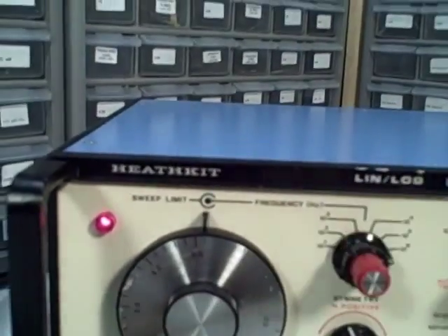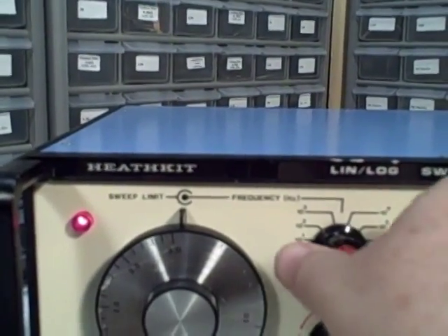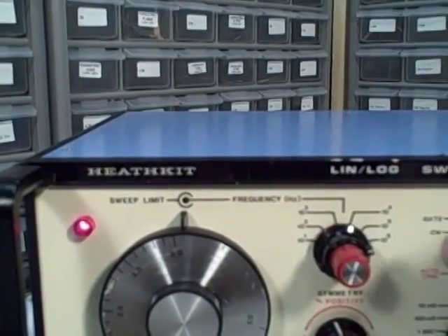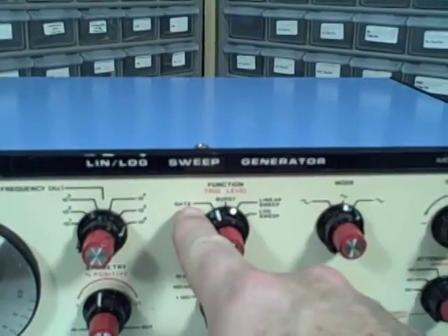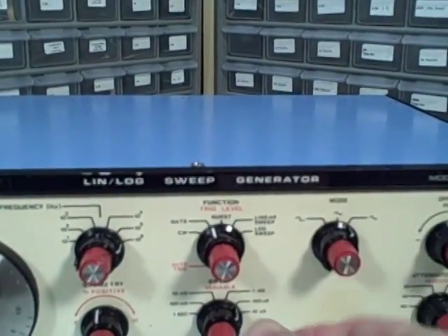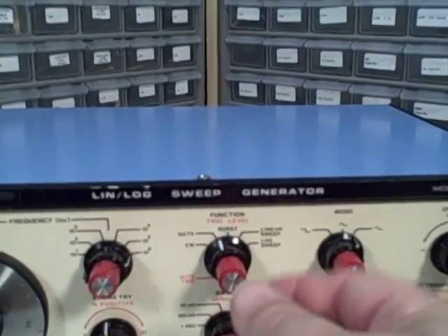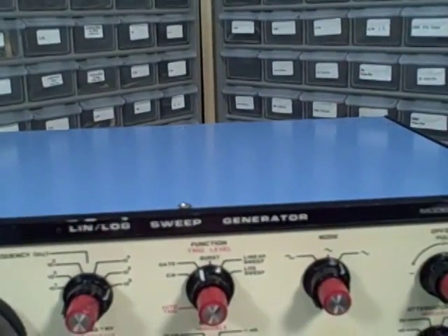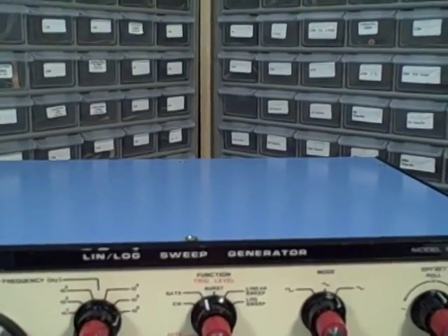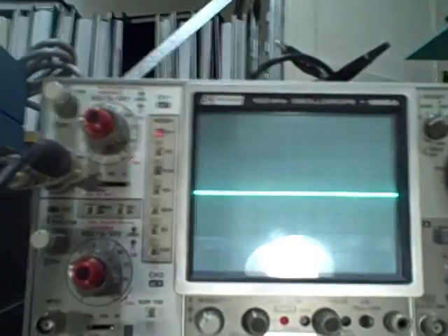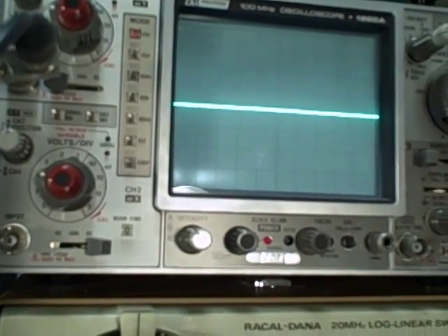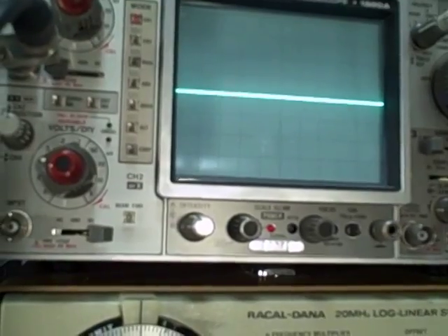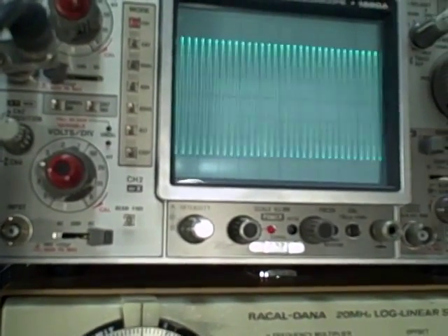So that takes us through the manual audio control of this thing. Let's go ahead and demonstrate what we mean by gate. The function is set to gate. I'm set on the sine wave, and I'm not sweeping, but I'm in the 3 million hertz range. I don't see anything on the screen at the moment, but then I'm going to push the trigger button. There. Push the trigger on, let it go, so I can gate it. That's what's meant by that.